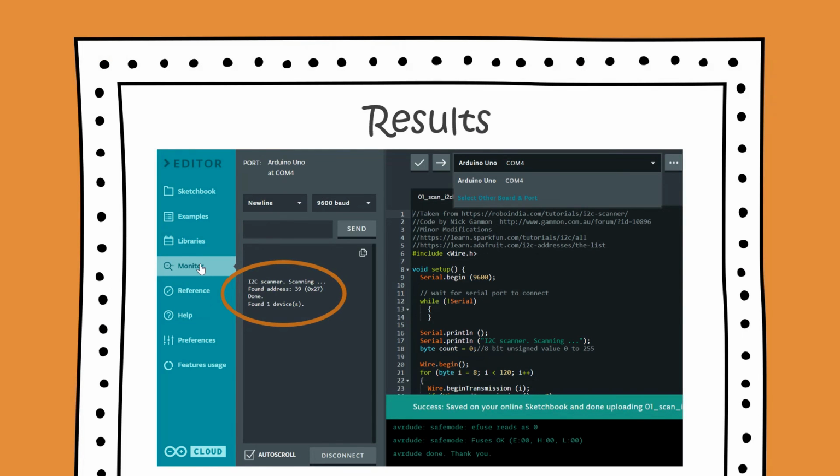So that's it for this video. The point to remember is that whenever we use an LCD screen fitted with this I2C chip along with the Arduino, we need to remember this address 0x27, and based on this address we would have to take a call on how we write the code.